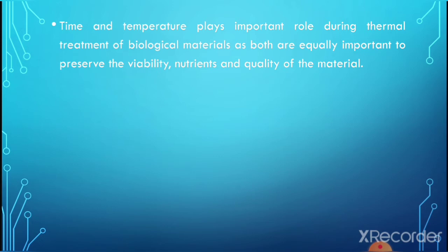So this process is nothing but the long time low temperature process, LTLT. So in order to kill the pathogenic bacteria from the milk, we must have some combination of time and temperature to kill that particular pathogenic bacteria.